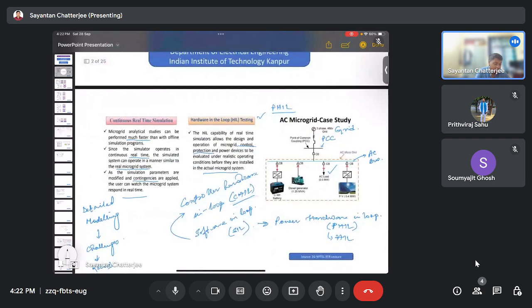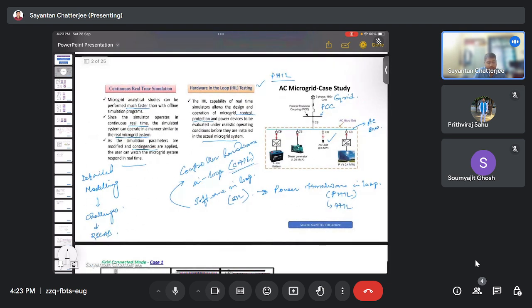The advantage of using a diesel generator is that once we are off grid, working in grid forming mode, the generator delivers the excess power, like the slack bus, and it also takes care of the reference angle of the system, because you have to have a reference angle to perform the load flow solutions.